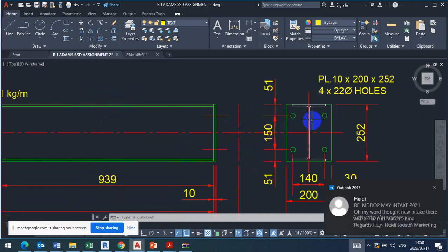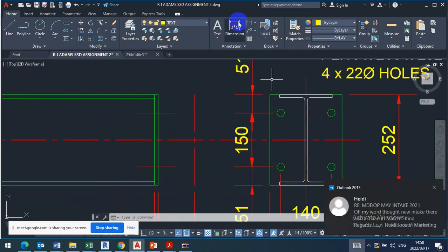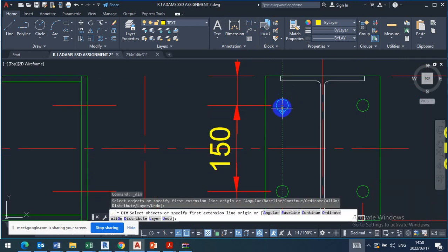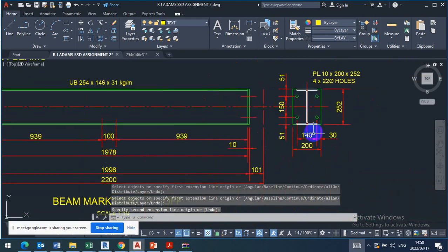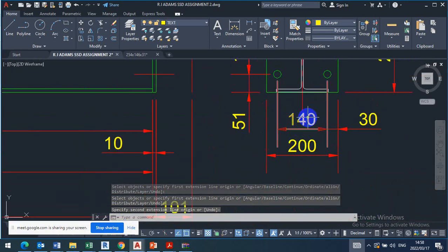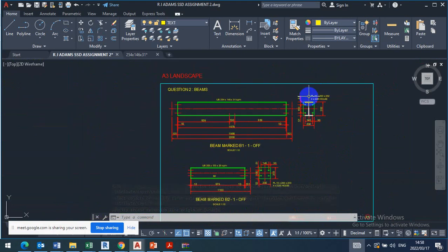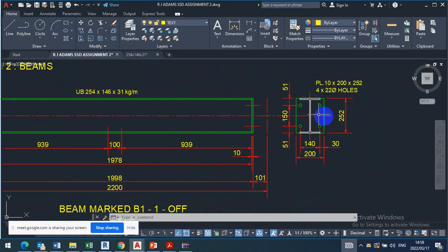Now my point is, how did he get the position, meaning the distance from this hole here to this one here? Whatever distance he got, because it's under the scale now, it's 140. Where do we get this distance? We call this one a gauge distance. A gauge distance is the distance from here to there, across the web.